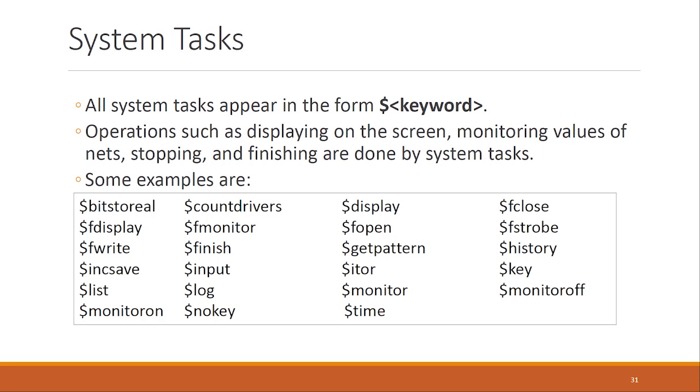There are examples given here in the slides of system tasks available in Verilog. $bitstoreal, $fdisplay, $fwrite, $kill, $list, $monitor, those are system tasks available in Verilog. And most often we will use the system tasks $display and $monitor.